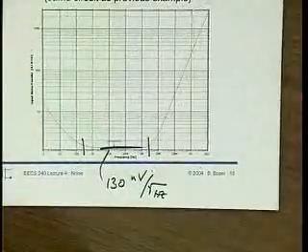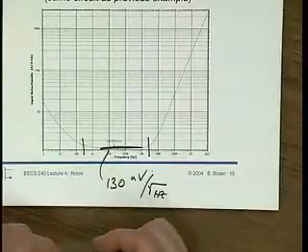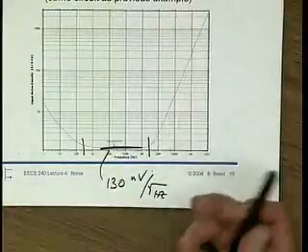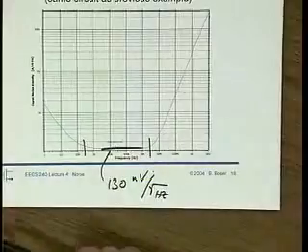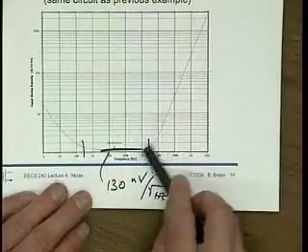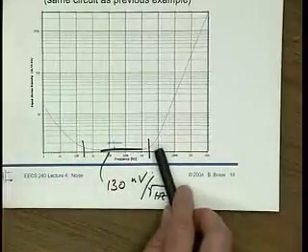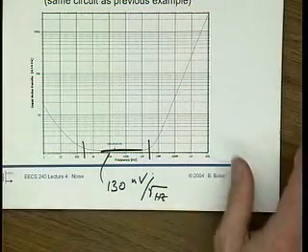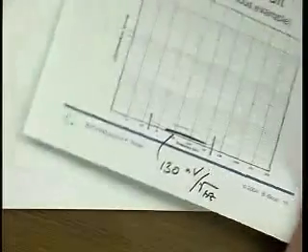It's totally normal. If it doesn't, and it's input referred noise, something isn't quite right. Now, most of the time we are not really interested here anymore. Why not? Because this is beyond the 3 dB bandwidth of our amplifier, and no signal comes out anymore. If we are concerned up here, then the first thing we have to do is get a faster amplifier, and then we can worry about whether there is noise coming out.